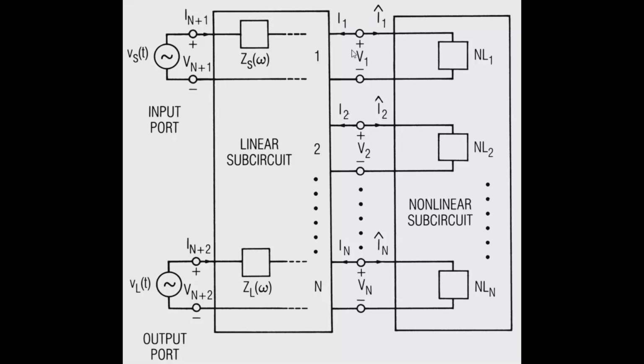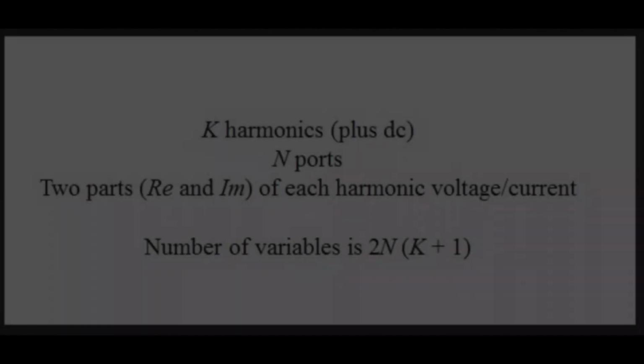So we have to modify these voltages in some way that will get them closer to being the same. And if we can keep doing that over and over again, then we'll eventually converge on a solution. So how do we do that? We use a method called multidimensional Newton's method, and I'll show you a little about that now.